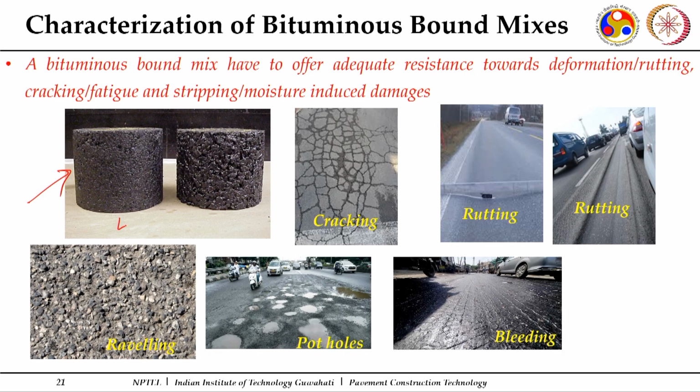Now these may be of 4 inches diameter or 6 inches diameter, varying from a height of 2.5 inches to 4 inches or even more than that. The conventional sizes normally used are 4 inches diameter and around 2.5 inches or 2 inches of height. So we will prepare these specimens and ensure some properties of these mixes so that they are resistant towards cracking and any deformation which can happen.